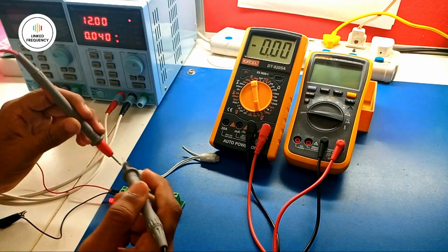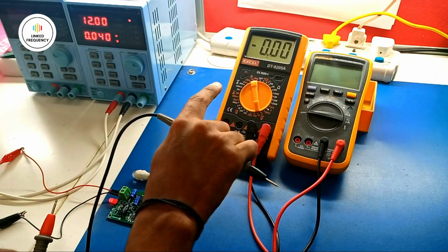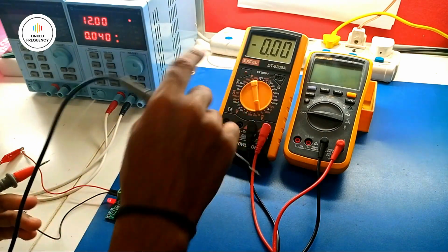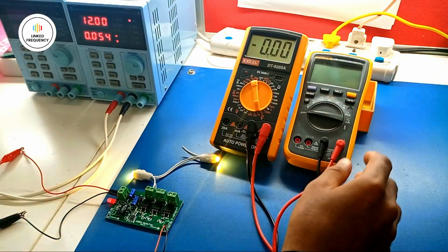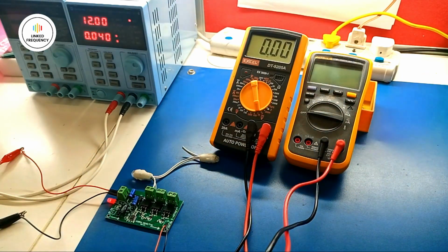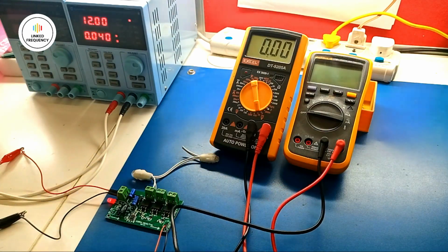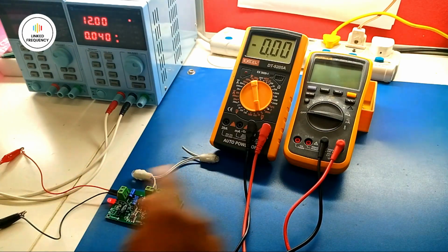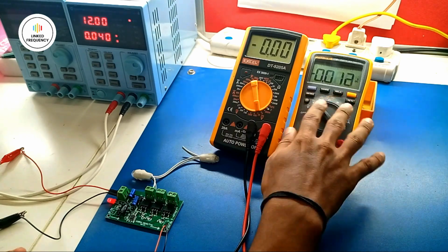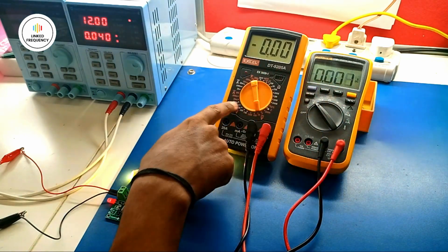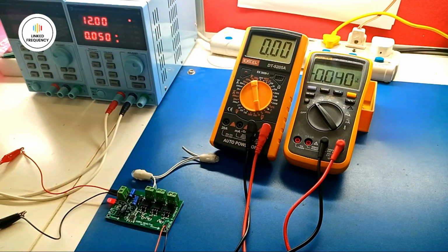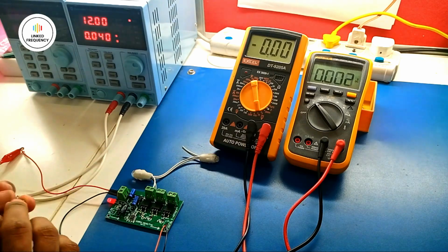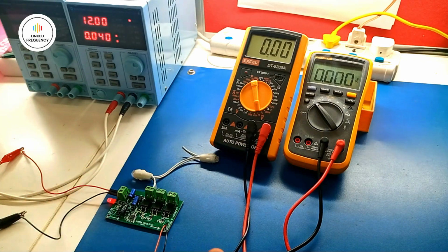Now if you want to measure the current, we have to switch from this positive to this side, then set the specific current rating in the multimeter and start measuring. Before that, let me show you how this multimeter will measure against the Fluke one. I'll use the positive and negative probe and set it to digital voltage. Here we have to set the range manually, because it is a lower-end meter, and we have to choose what range of voltage or current we are measuring, whereas in the Fluke multimeter we already have dynamic ranging, or you can say it is automatic.